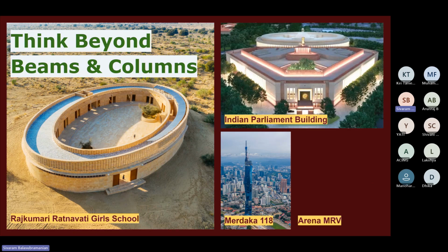So that is one way you can bring in your models. You can also export an Archicad model into RVT format. You can also read RVT files in Archicad, but there would be a little bit of mismatch within the classification here and there. I can say Autodesk and Nemetschek have collaborated to make this process much easier.